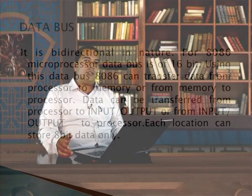Now, let us discuss something about this data bus. This data bus is solely responsible for carrying the information from memory or IO into the processor. As we all know, when the processing starts, the first job for the microprocessor is to fetch the opcode of the instruction into the processor for decoding and further processing. Now, this fetching of opcode from memory is done with the help of this data bus only.